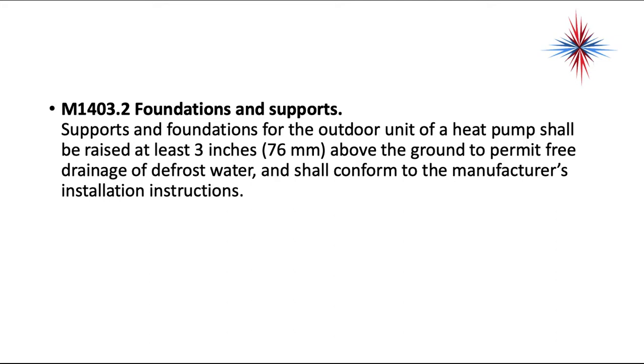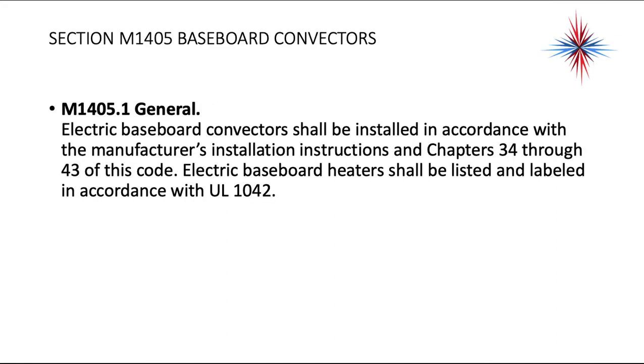However, heat pumps have to be installed on an outdoor support, usually a concrete pad, that needs to be 3 inches above the surrounding ground area, because there has to be drainage around heat pumps. In the northeastern or northern parts of the country where snow gets on the ground, it is actually raised further per manufacturer's directions.